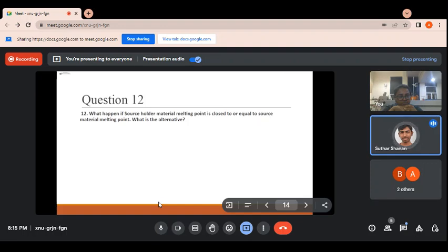In week 4 it was spin coat, soft bake, hard bake, UV exposure, and then you again bake at 125 degrees or above. But in the week 8 assignment, it says first soft bake, then UV exposure, and then hard bake. So both are SU8, but the procedure is different. So that's why I am asking.